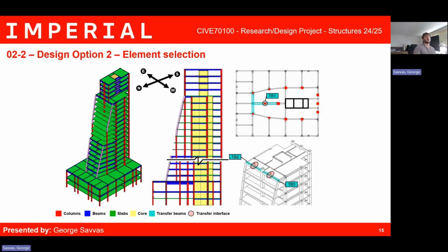Levels 3 to 9 use beam slabs throughout, while levels 9 to 18 adopt a mix, flat slab to the north and beam slabs to the south. Between level 9 and 12, raking columns are interrupted to provide open views before being reinstated. At level 18, transfer beams allow conventional beam slab construction up to the roof.